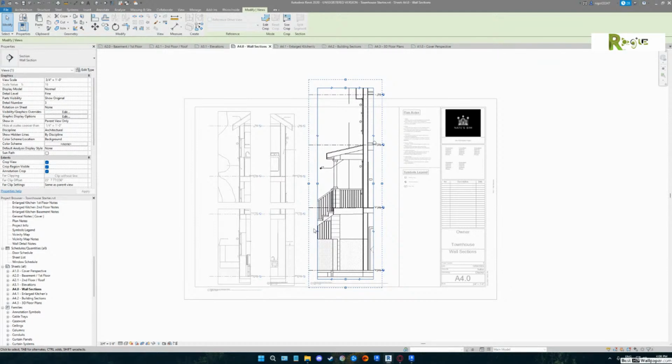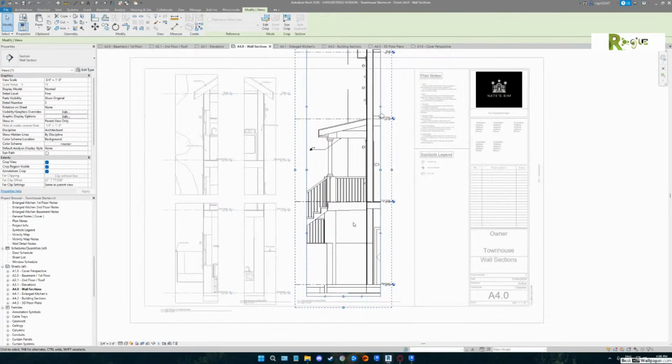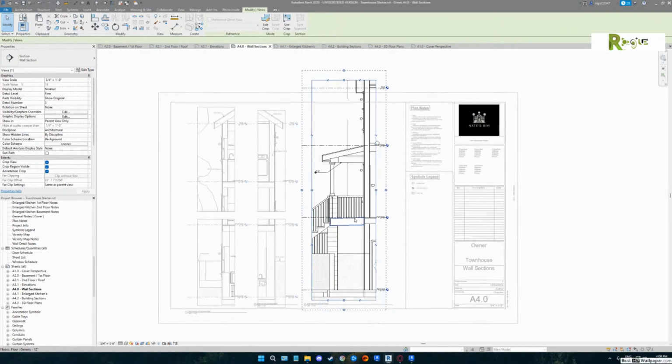I would want all of that porch and all that stair detail like you got. I would break it up above the porch roof. Right here. And I might just pull that top boundary down until it's on the page. A little bit more, maybe. Yep, right in there. See how I want that lined up with the one across from it.